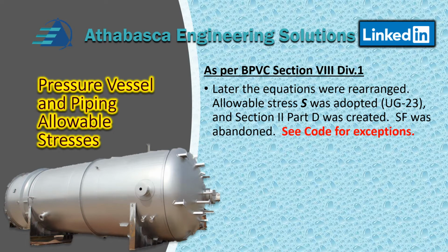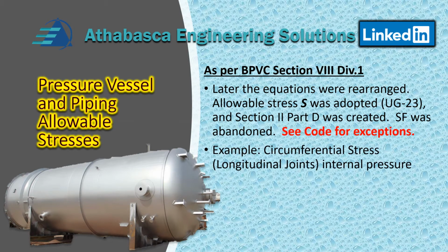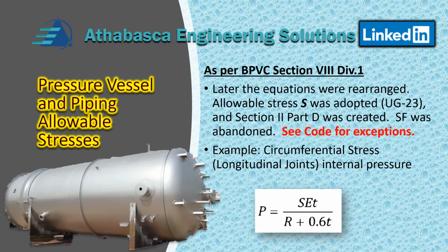Below is an example of an equation, one of them, circumferential stresses, which is a longitudinal joint internal pressure equation. And you can see how S has now been replaced, and a few other variables have been added, like the efficiency of the weld and the thickness. The equation is more developed. And basically that's it. And you need to see codes for exceptions.